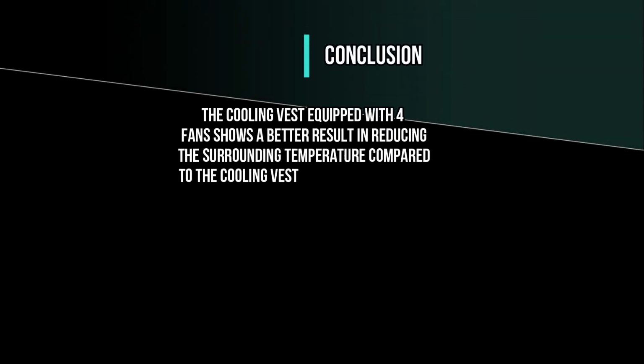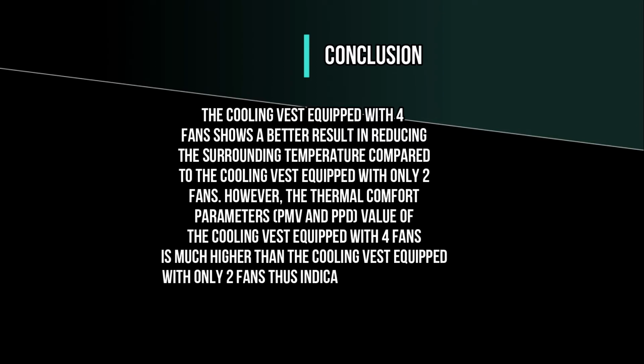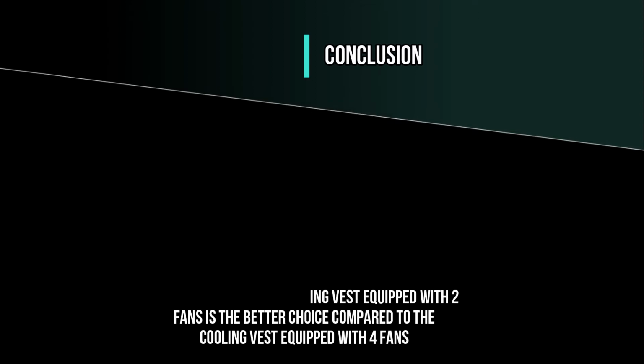In conclusion, the cooling vest equipped with 4 fans shows a better result in reducing the surrounding temperature compared to the cooling vest equipped with only 2 fans. However, the thermal comfort parameters PMV and PPD value of the cooling vest equipped with 4 fans is much higher than the cooling vest equipped with only 2 fans, thus indicates that in terms of thermal comfort, the cooling vest equipped with 2 fans is the better choice compared to the cooling vest equipped with 4 fans.